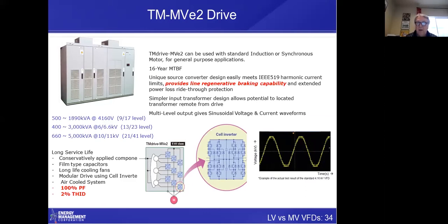and that's an exciting thing. We had a wind tunnel once where the motor was suspended in the middle of the wind tunnel, and we had a motor quote, we had a drive quote, but every pound was important. We talked to the motor manufacturer and said, is there any way that you can reduce the weight of this motor? Well, that's kind of tough, but they said, well, show us your output voltage waveform on the drive. We showed them this waveform, and they said, oh man, that's like a sine wave. They took, and I think this was a 3,000 horsepower motor, they took 2,000 pounds out of that motor, and that was all insulation because of the output waveform.